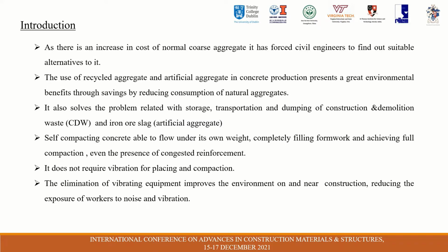Here I have used a special concrete, SCC, where the SCC has an ability to flow under its own weight, completely filling formwork and achieving full compaction, even in the presence of congested reinforcement. It does not require any vibration for placing and compaction. Eliminating vibrating equipment improves the environment on and near the construction site. It reduces the exposure of workers to noise and vibrations.